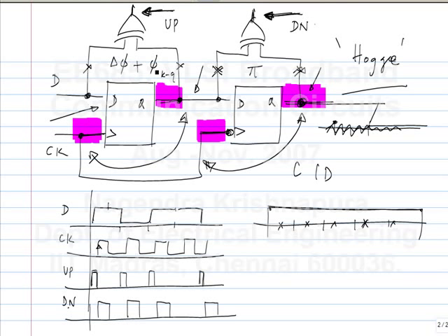So the advantage is it can work for high speeds. It's a simple circuit, etc. But the disadvantage is that at extremely high speeds, when the clock to Q delay becomes comparable to, let's say, a significant fraction of the time period, then you have a significant phase offset in the phase detector. Okay.